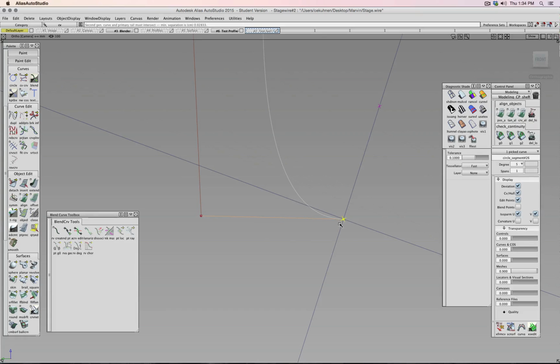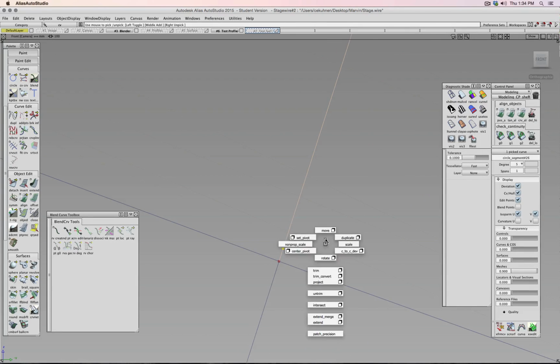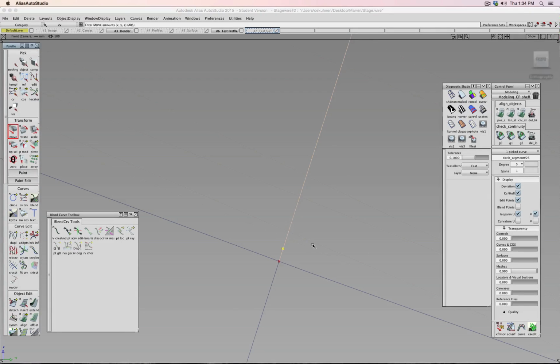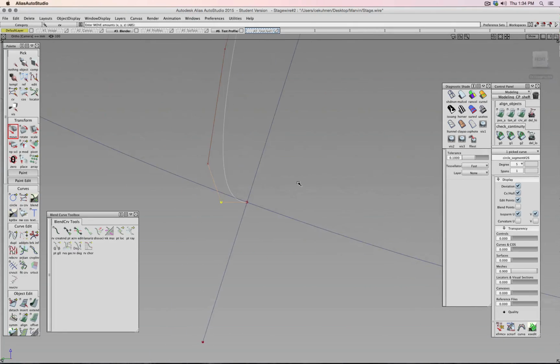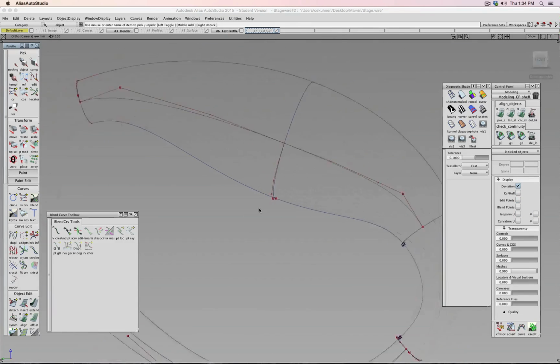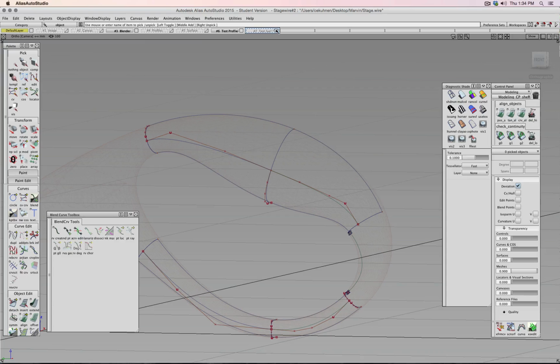Select the CV and move it to here. Move it to where it intersects. Select the CV. Now I go move, up and down. Let's select move and control, middle mouse button and control. So they're lined up again. I could also, of course, simply have drawn lines out and then snap those ends to it. This worked as well. Let's go back to our surface.